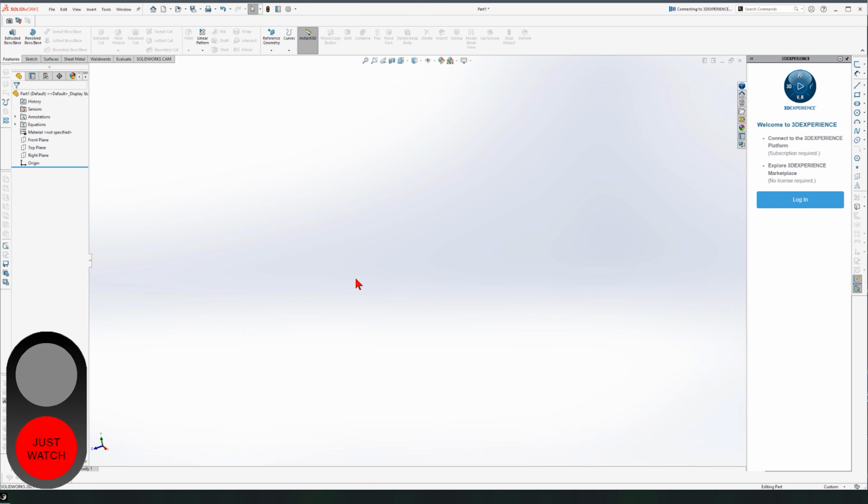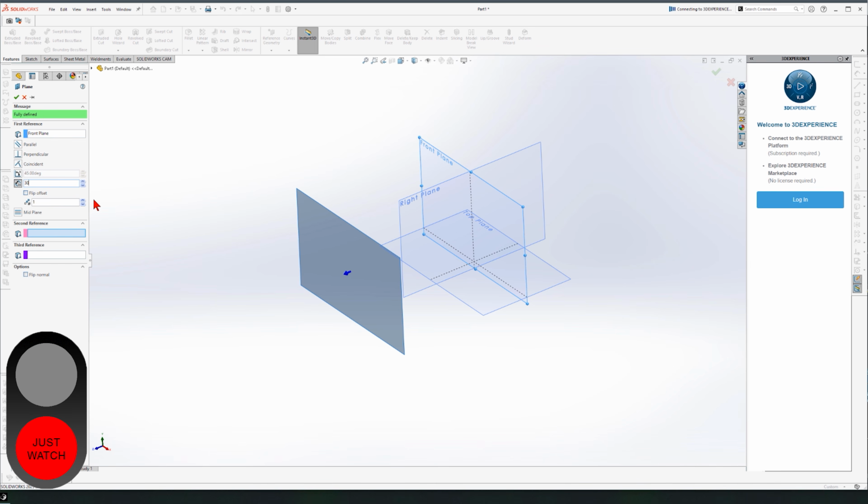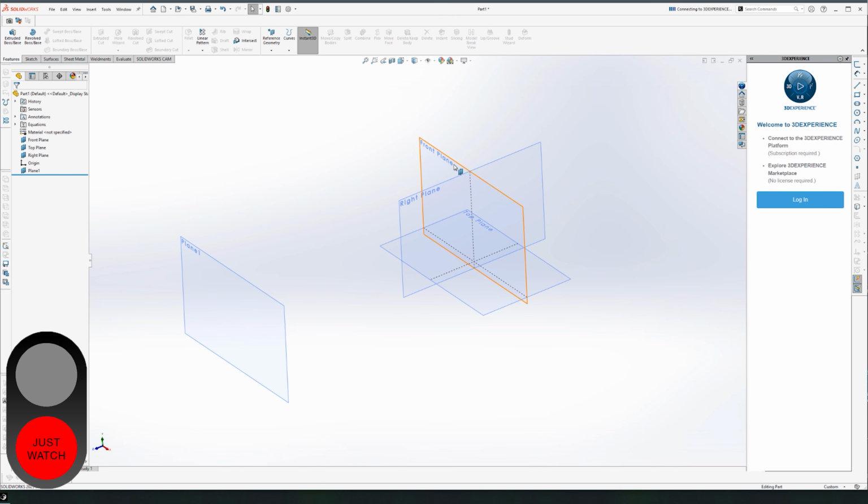create a custom plane, because we have 3 default planes over here, right? Top, front, and right. And I want to have another plane, say right about here, parallel to the front plane with a distance of, say, 300. So if I create another plane here with a distance of 300, you might be asking yourself, wait, how did you just drag one plane out of this plane? When I do this, this doesn't happen. Exactly, it doesn't happen. And there is a technique to do this.